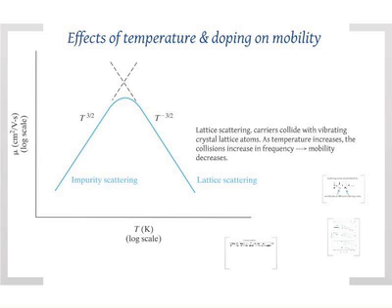This deceleration induces a force which balances the acceleration, and you get a steady state velocity, which is described by the mobility. Now, if the temperature increases, the lattice vibrates more, which means it will collide more. Deceleration increases, which means the velocity decreases, which means the mobility decreases. That's the qualitative way to understand it. Quantitatively, we won't derive it, but the temperature dependence goes something like that.